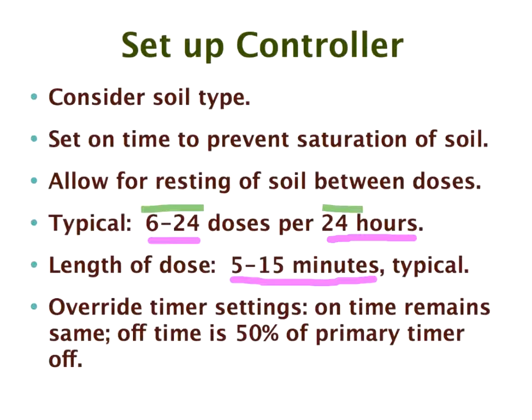And that reduces the incidence in which the top float goes off, and when the top float goes off, the alarm goes off. And of course, if you're connected by wireless to a central station, then the alarm will go off in the central station, and the maintenance people will know that something's gone wrong.